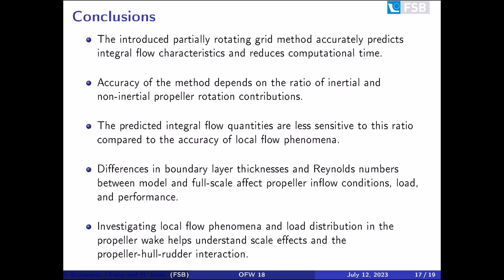Although the predicted integral flow quantities are less sensitive to this ratio, the accuracy of local flow phenomena is more affected. Differences in boundary layer thicknesses and Reynolds numbers between model and full-scale conditions have notable impacts on propeller inflow conditions, load, and performance.